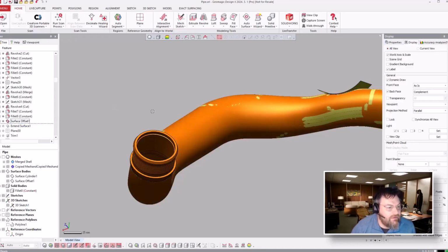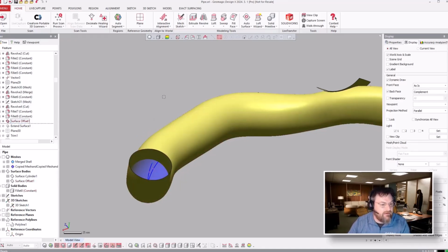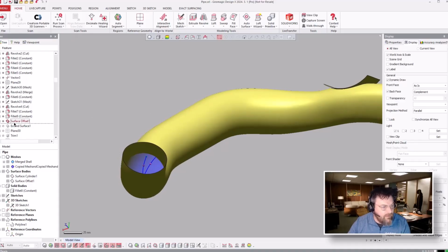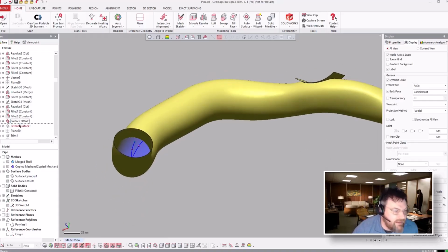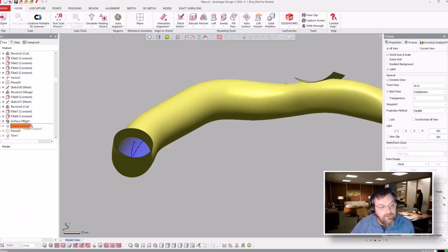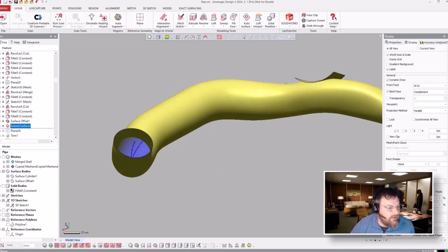That's actually a really good little tip for anybody out there that's done a lot of modeling in DesignX, that you can do this surface offset 0 to copy a face from a solid. There probably are other creative ways of doing it as well, but that's an important thing to pick up. That's a nice little tip or trick that we're learning on the fly here. That's nice.